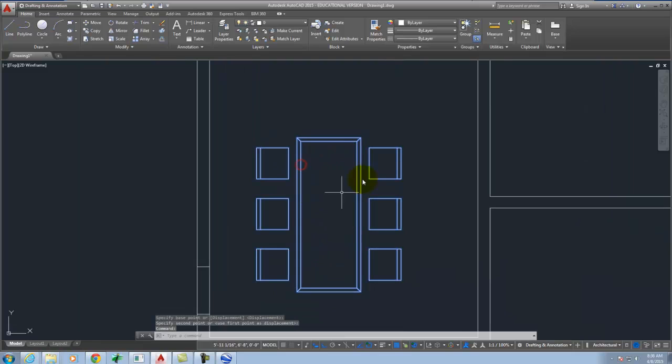And so this is what's called a block reference. Basically I'm referencing that other file. Because it's a block reference, though, I have to keep the other file on my flash drive. So don't just put it on the desktop and then delete it, right? Save it with the rest of your work on your flash drive, okay?